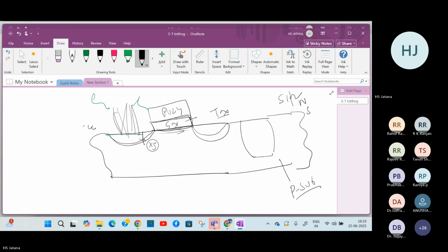Sir, is there any source for this SPICE file for SCL 180 nanometer? Yeah, you can ask. It will be there in the PDK. If it is not there, you can ask them. They will give. TSMC is providing this for academic use. You can take. I think it's there in the PDK. You can open it in a notepad. In the SPICE file you can see various parameters. There are around 80-90 different parameters. Their name is there, the value is written. Those values are given there.